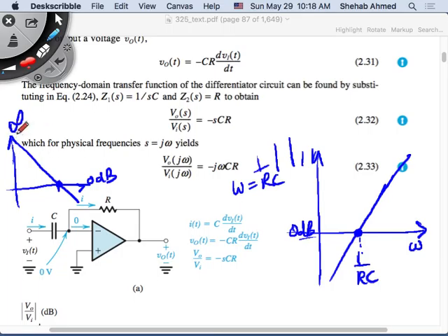So what did we do to solve that? We put a resistor in parallel to limit the gain at low frequency to some value, and then attenuate everything after that, right? Why did I do that? So that allows me to put a DC into the integrator and be able to do my work. If your signal happens to have some DC content, you want to have a limited gain for that content. You don't want something to go out to infinity, uncontrolled, right? But if you're able to control it, then you have a result, right?